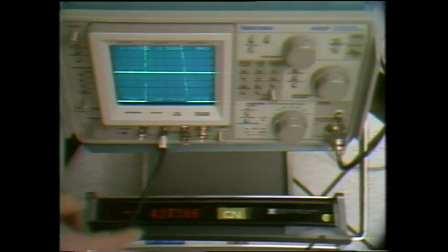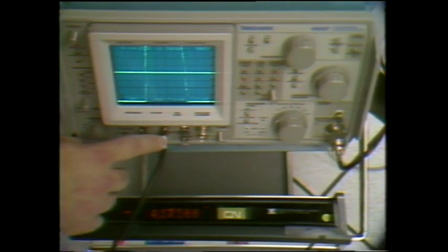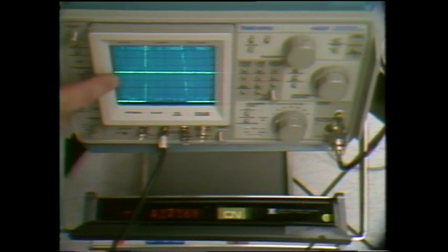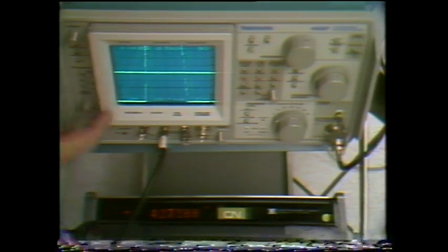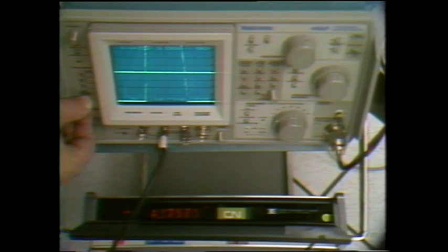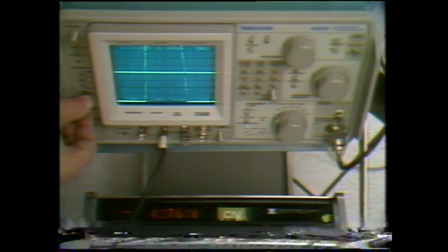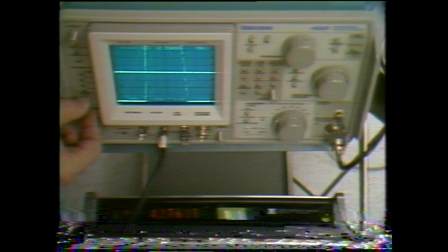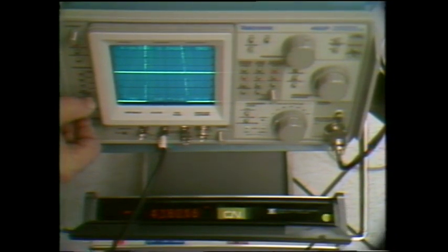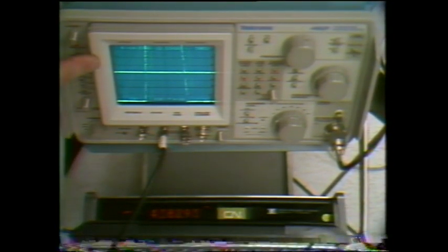To get a more accurate frequency reading, we have to attach a counter to the local oscillator output on the 492. We then move the cursor down to the minus 50 dB point on our main lobe, and by moving the cursor from one side of the lobe and noting the reading on the counter to the other side of the lobe, and once again reading the counter, we take the difference of these readings, and since we're on the n equals 3 band of the analyzer, multiply this difference by 3, and we come out with a 19.83 megahertz frequency band.